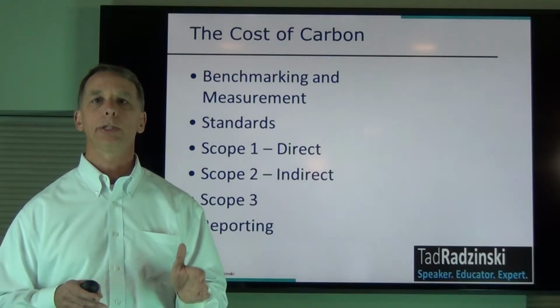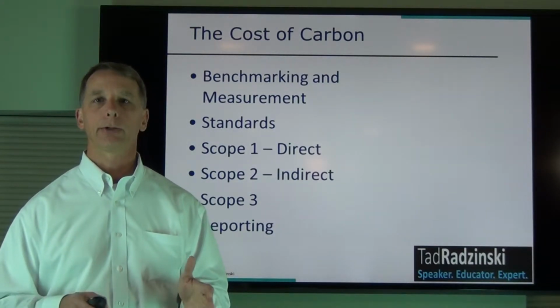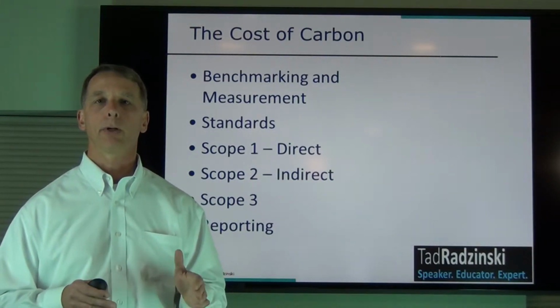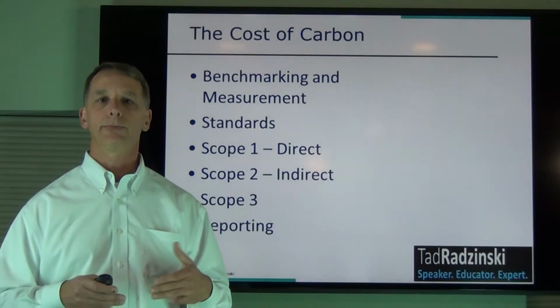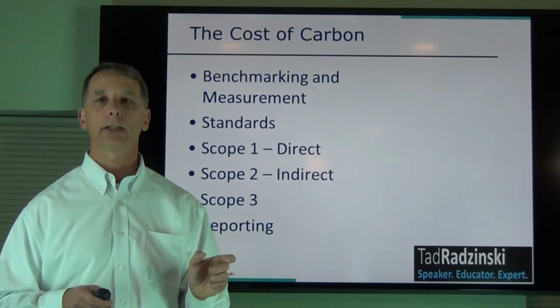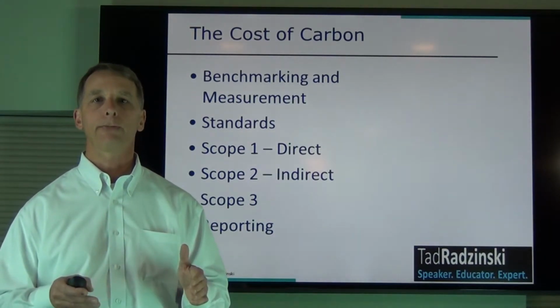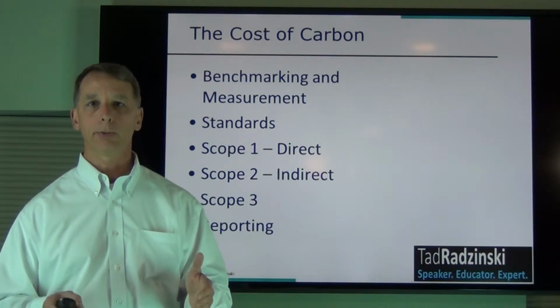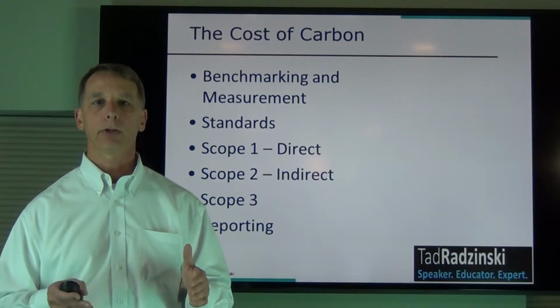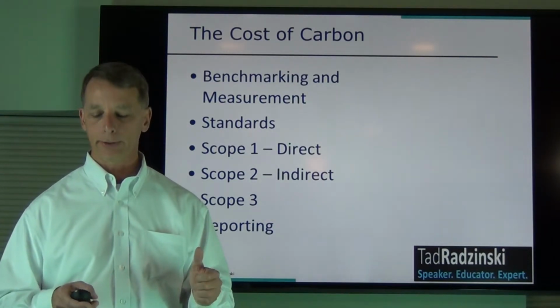You also need to know the EPA emission factors for various fuels. For example, if you're burning natural gas, you would follow an EPA emission factor to calculate the CO2 equivalent emissions that would come off of every MMBTU of fuel that you would burn. These are all posted online, and you can definitely find information about these.